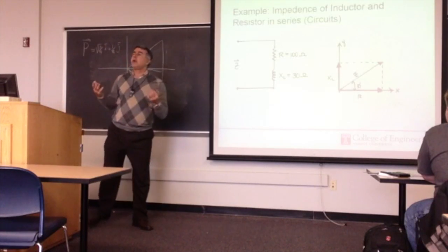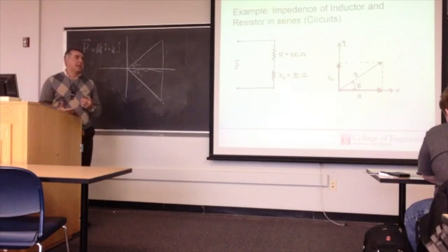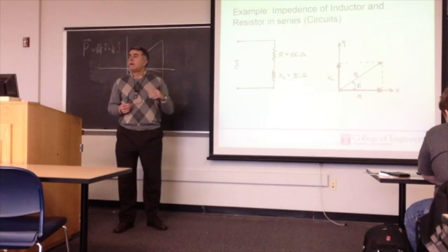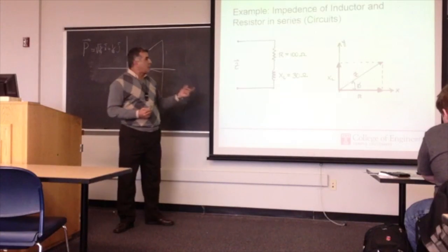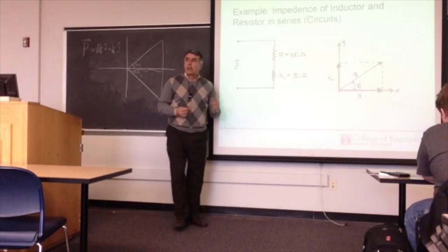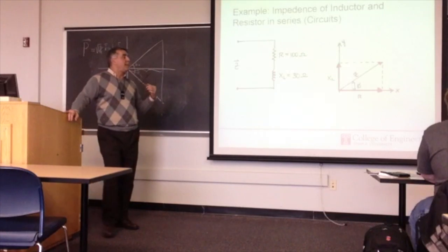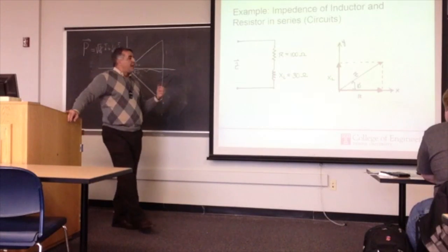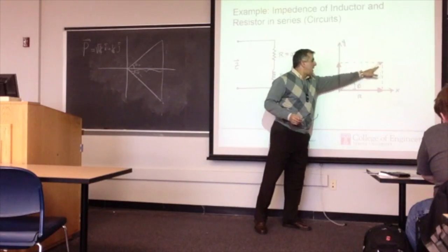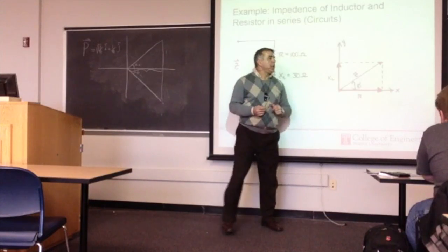When you get to know electricity, you will see that there is a phase difference of 90 degrees between a resistor and an inductance. That's why, when I want to find Z, which is an equivalent resistance, or in this case what we call an impedance, Z simply is a vector representing the resistance and the inductance.